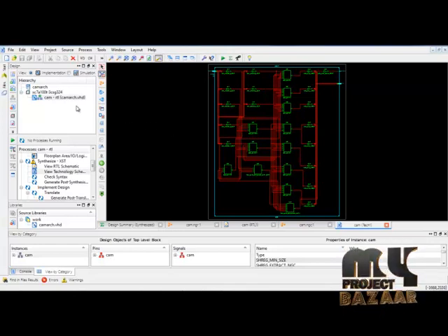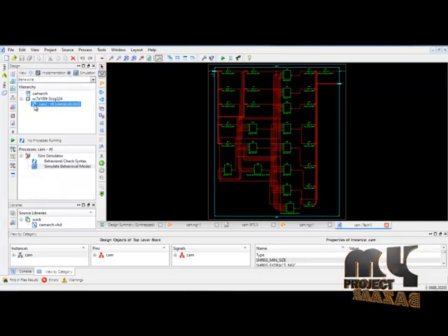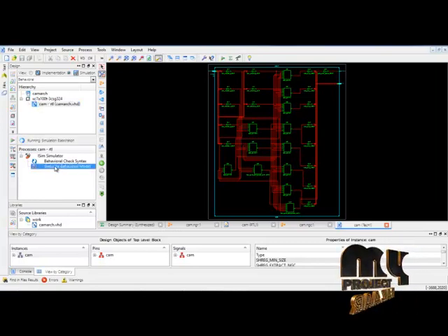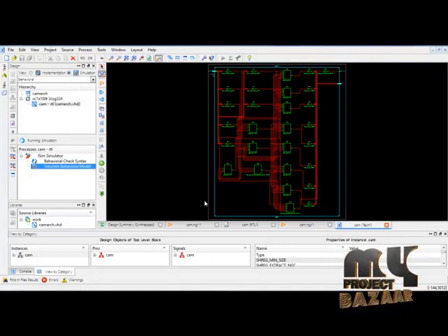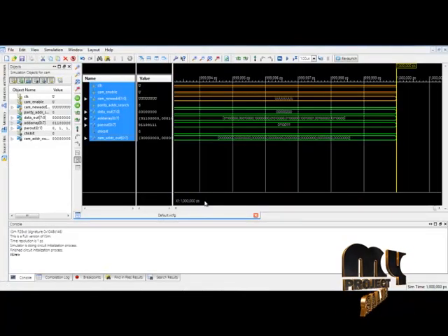Then we can view the timing diagrams of the output by selecting the simulation option and selecting our main code. Then click Simulate Behavioral Model. This provides the timing diagrams for the logical design. In this case, it will create a GUI. Here I am using ISim for visualizing our outputs.